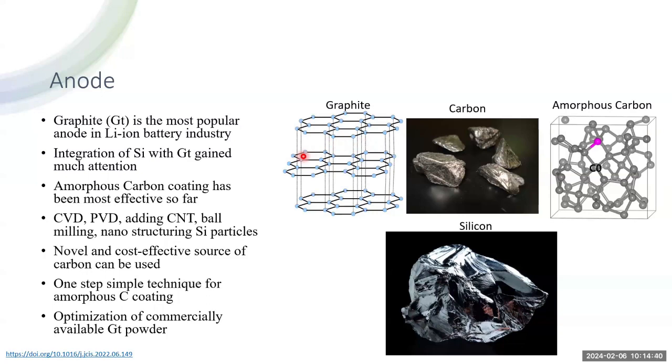This is slippery. Why? This is because of the internal structure of the graphite. Actually, the layers of the graphite stay like this, one after another in a hexagonal structure. That means this upper portion is the hexagonal part, and the lower hexagonal part has a gap in the middle of it. And this gap is about 0.14 nanometer, well enough to hold a lithium ion inside it, because the lithium ion is much smaller than this gap.